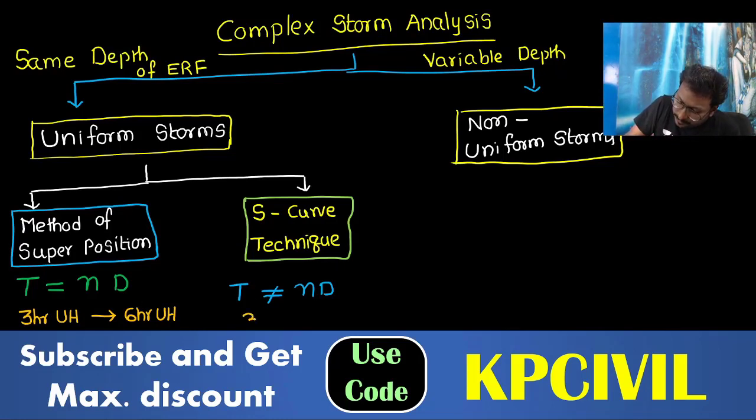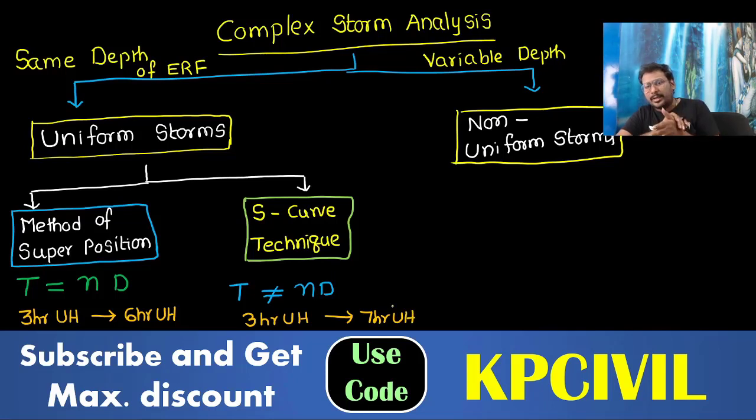But if you want to convert a 3-hour unit hydrograph to a 7-hour or 8-hour unit hydrograph, time is not divided into equal periods. 3-hour, 6-hour, 9-hour, 12-hour UH you can plot, but not a 7-hour or 8-hour UH. With variable time, n equal periods is not possible. That is analyzed through the S-curve technique.